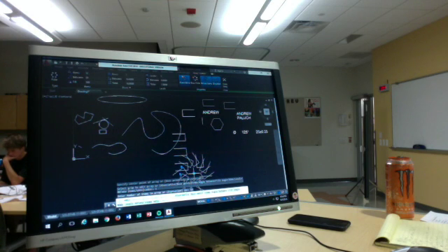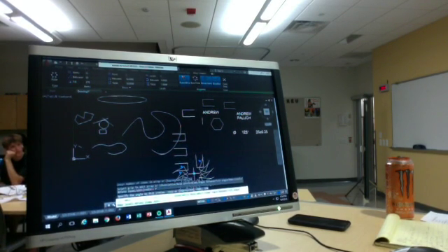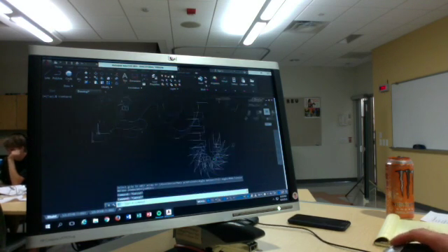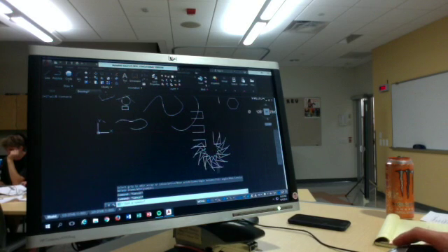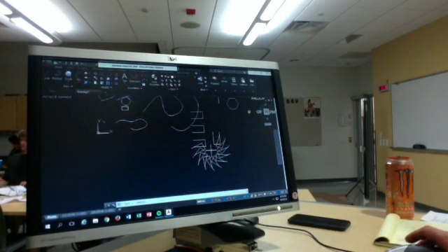You can also change the fill angle. So type in F. That's going to change your fill angle. It's assuming we're going to do a full circle. Let's say I only want 3/4 of a circle. That's 270 degrees, as we know. Type in 270. It fills in 270 degrees' worth. Just like any other command, in order to exit out, you hit enter. But you have to make sure to complete the command. So there's my 12 items with the center point being in here, on 270 degrees' worth of rotation.